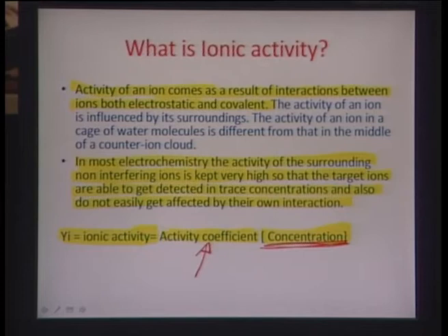And so therefore, especially in MEMS kind of protocols, where we are talking about selecting over a very small volume of liquid, there is almost always a tendency of the activity to be very much different than the concentration. And so we are next going to find out how it is possible, by designing an electrode, to pick up a certain ion over, let us say, several competing ions, and that is how we get into the field of ion selective electrodes.